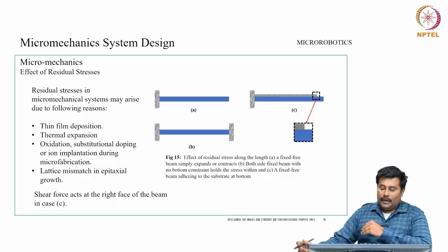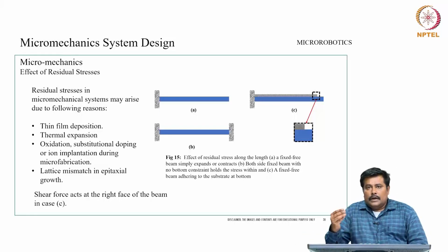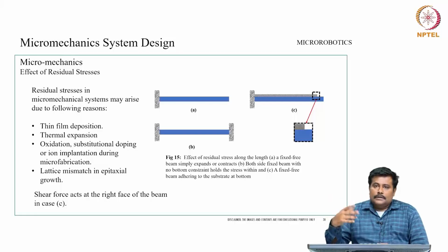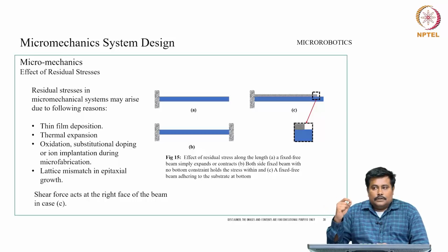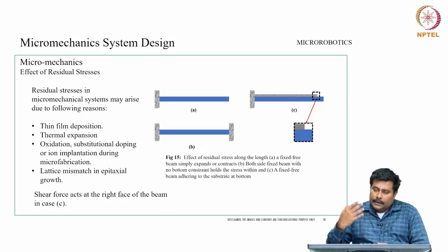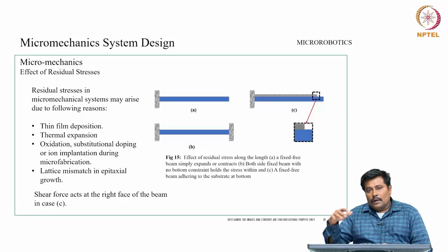In the last lectures, we have been discussing this unimorph and bimorph concept, and the usage of unimorph and bimorph in different smart material based smart actuators. Like we had discussed the shape memory alloy bimorph, and also the piezoelectric based bimorph. In the case of piezoelectric or shape memory alloy bimorph, we had discussed that the degradation of these actuators basically depends upon the continuous actuation as well as the continuous overloading of residual stress. So, this effect of residual stress has an impact on the overall life cycle of the actuator.